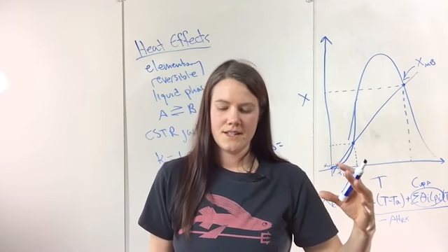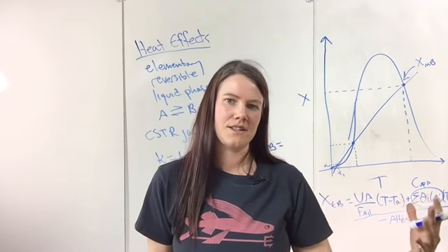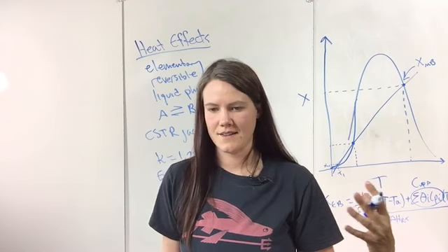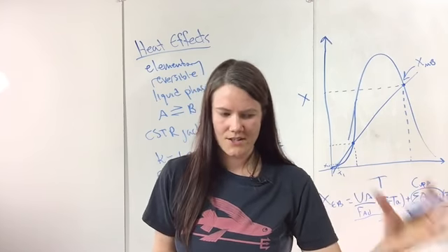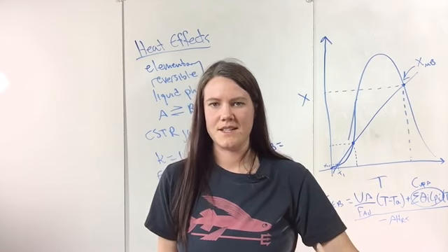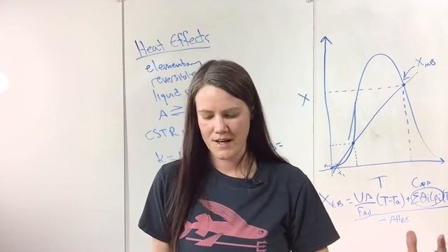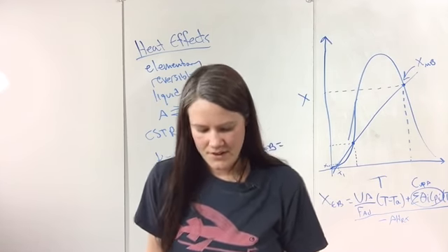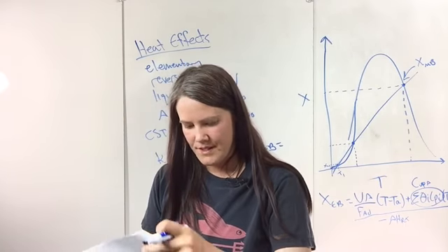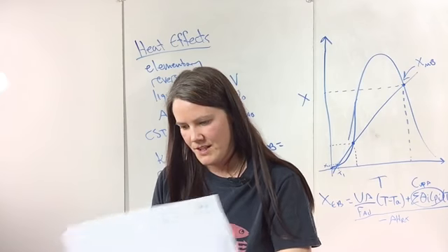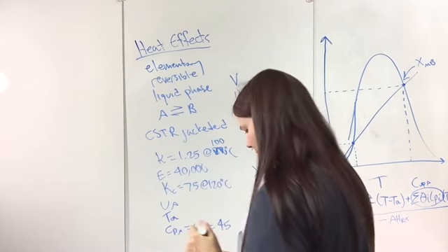So the effectiveness factor is what you actually got divided by what you would get if it was ideal. You can calculate that and multiply it by your rate law to calculate what you're actually getting. And I wanted to go through an example problem with that.